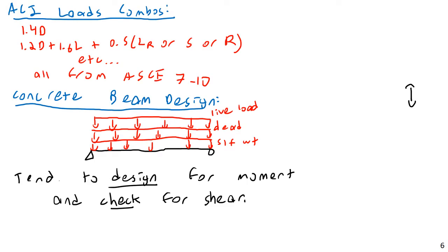Again, that's what usually governs our design. All design always occurs in levels of iteration loops, where you come up with an initial design, you recalculate your loads based on that, including self-weight, then you say, okay, this is either too strong or not strong enough. If the member is way stronger than you need, say your allowable load is twice your actual factored load, then you might want to lighten the beam or column, whatever it is. But then you'll have to readjust things, and your load changes.